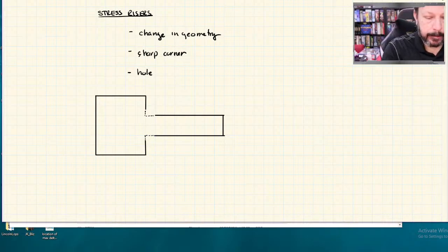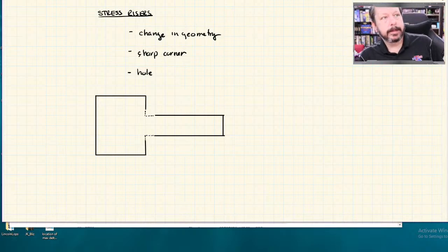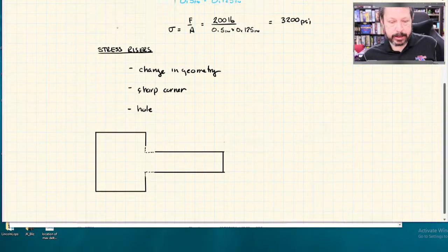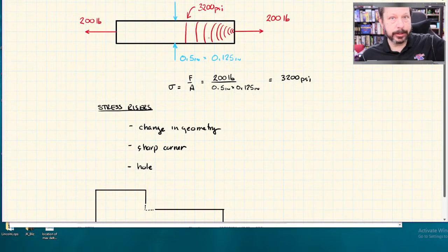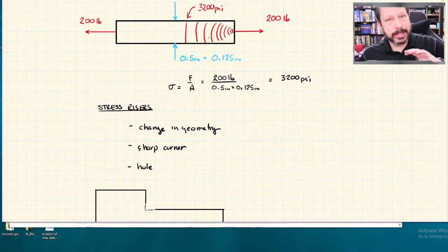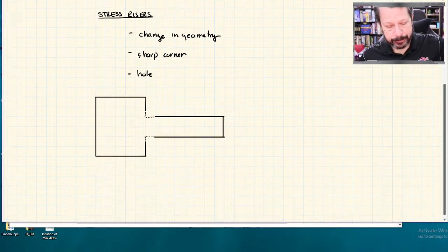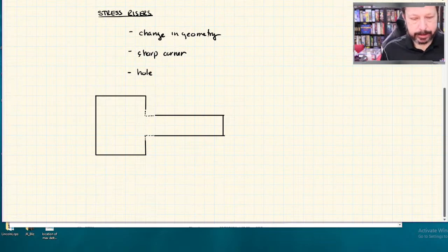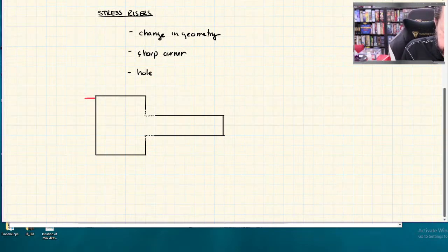So if you think about the way the stress has to flow through the object, for our objects that we've been dealing with, they're just kind of longitudinal, or they're pretty straight. And so the stress has a direct path to develop throughout the whole thing equally. But if I've got, let's put a distributed load over here to avoid the situation of the point load and its stress concentration.